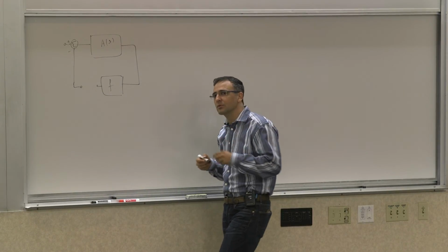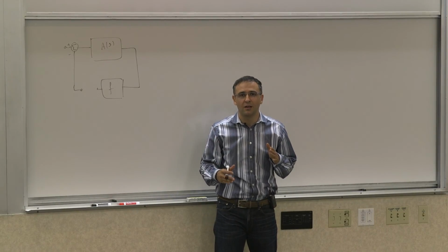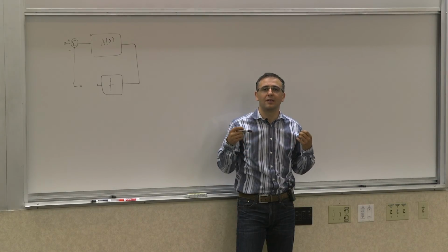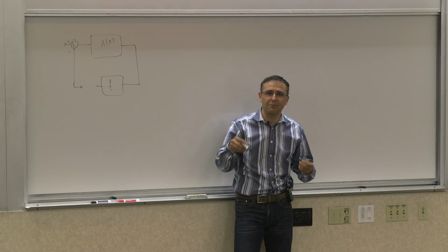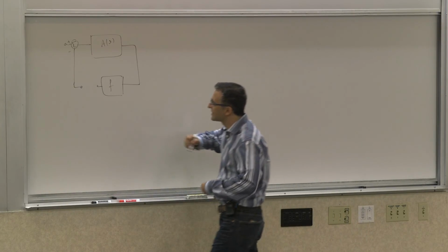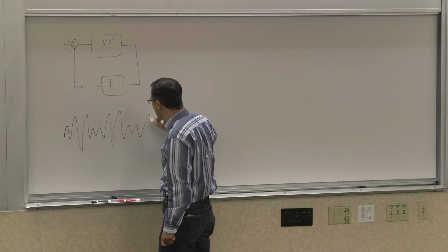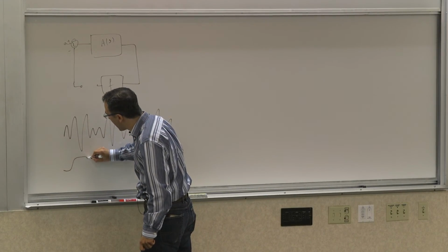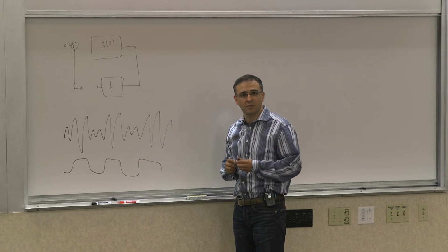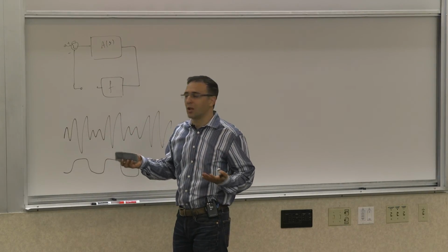Now the trick to oscillation: think about a sustained oscillation. In more technical, accurate terms, we are looking for limit cycles in the system. Stable orbits, basically, something that the system goes through. So a stable oscillation in the sense that it produces a stable waveform. It doesn't have to be sinusoidal, but it's stable. It can be something like that, or something like that, but it doesn't grow and it doesn't shrink over time. It stays there, and that's the nature of a reliable oscillator.